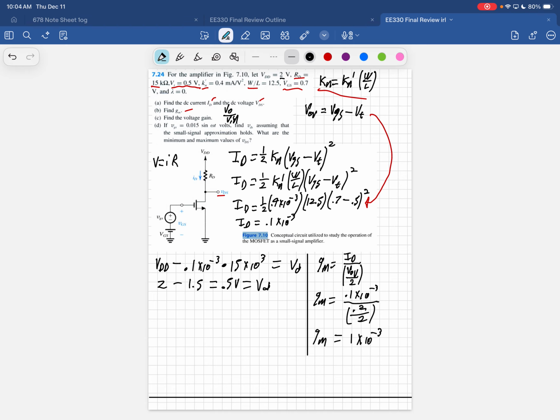The gain is always going to be negative. So what you can do is you can go through and memorize or write down how to get the gain for each one of these amplifiers based off of GM and the resistor, or in the case of other amplifiers, GM and other configurations of transistors. The way I did it in school was I always just found it based off of your equations here.